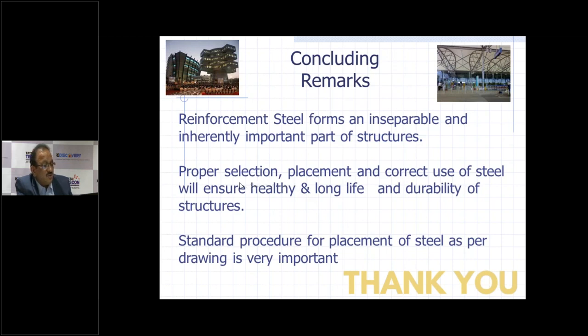Now this is the last question I am taking, from Charanpreet Kaur. He wants to know, can we provide additional reinforcement for reducing the bending and shear force? Is there any IS specification for that? See, additional reinforcement is not going to help you, because in the design it is always preferred that we provide an under reinforced section rather than an over reinforced section, because in an over reinforced section there is a sudden failure. So we never try to put more steel reinforcement for increasing the efficiency of the structure. In fact, under reinforced structures are preferred, because you get advance warning by cracks which appear in the structure because of the loading. So it is always preferred that we should have an under reinforced section.